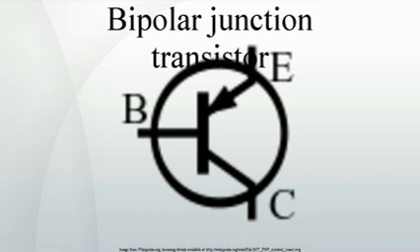In the more traditional BJT, also referred to as homojunction BJT, the efficiency of carrier injection from the emitter to the base is primarily determined by the doping ratio between the emitter and base, which means the base must be lightly doped to obtain high injection efficiency, making its resistance relatively high. In addition, higher doping in the base can improve figures of merit like the Early voltage by lessening base narrowing.